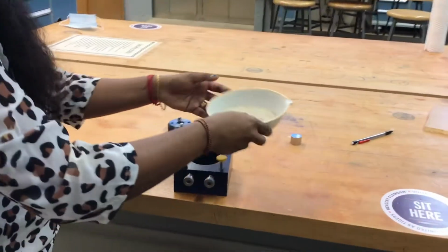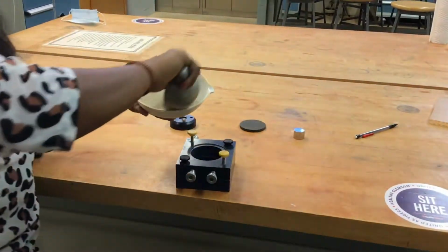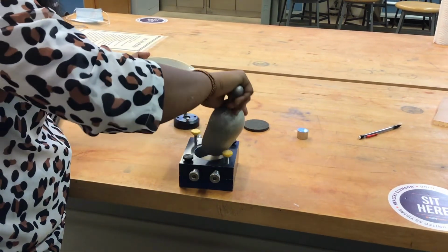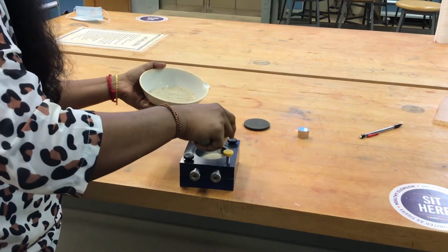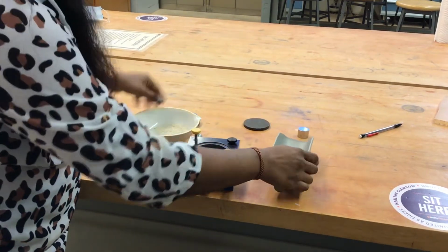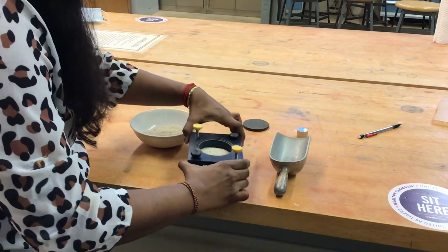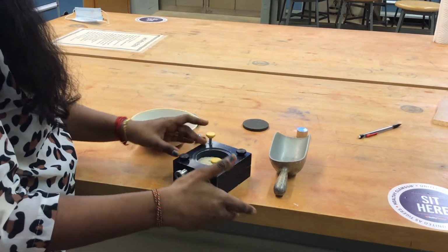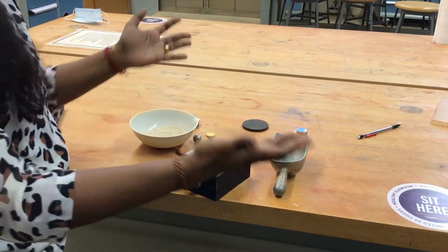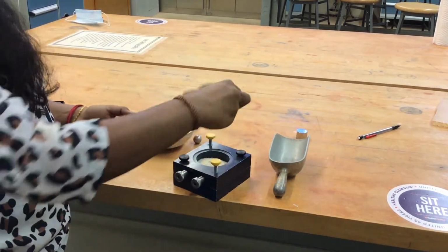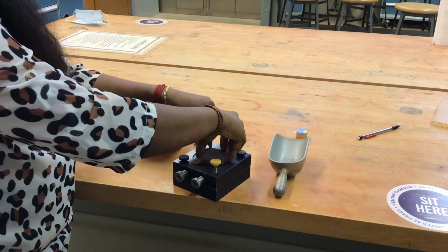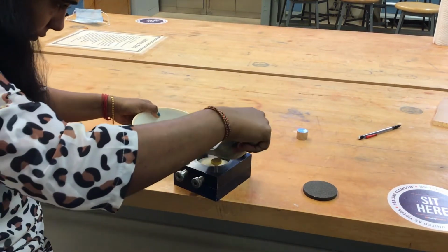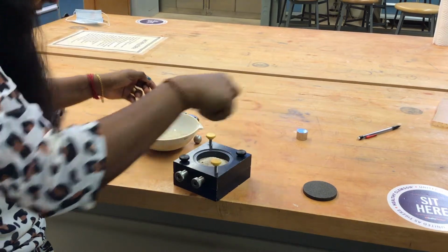Now I'm going to pour this soil into this apparatus so that I will have space for the porous plate, which will be coming on the top. So I'll make sure it is loosely compacted so that we can get the soil strength properties of loose soil. If you want to compact it more, then you can get the properties for the dense soil. So there will be a porous plate on the top. So leaving a space for the porous plate, we can fill the soil into this specimen.